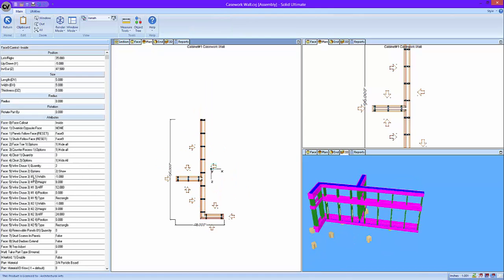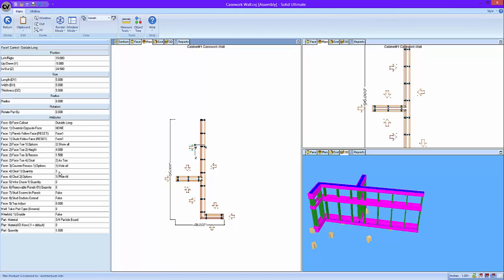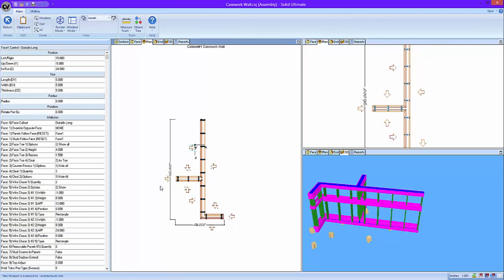We're actually going to get rid of the wire chases from here because I had set all these faces to copy this outer face, just to save myself the maximum number of things that I have to do. There we go. We will make the top one a circle. And let's just move it up to, say, 34.